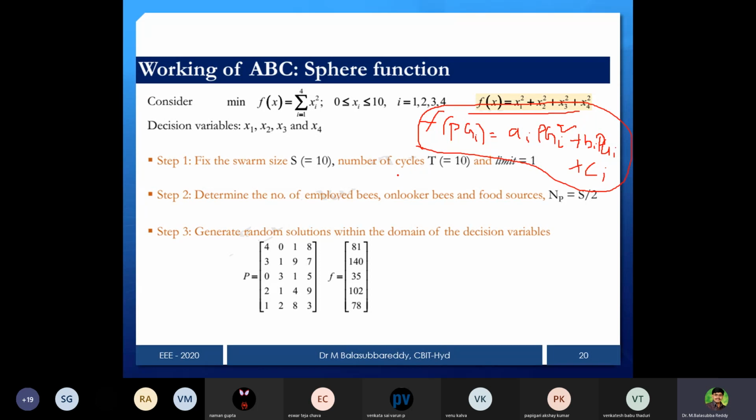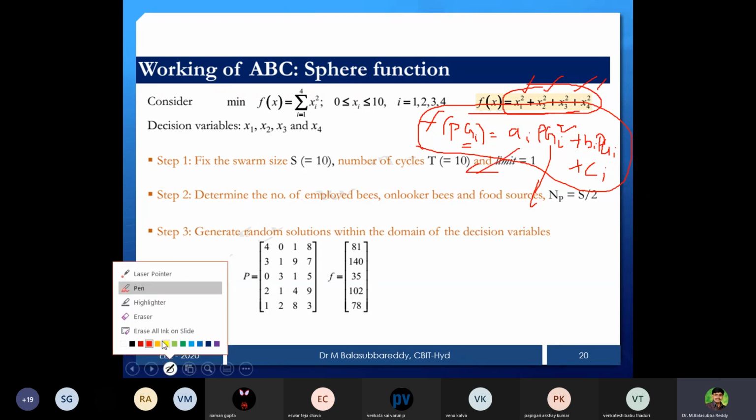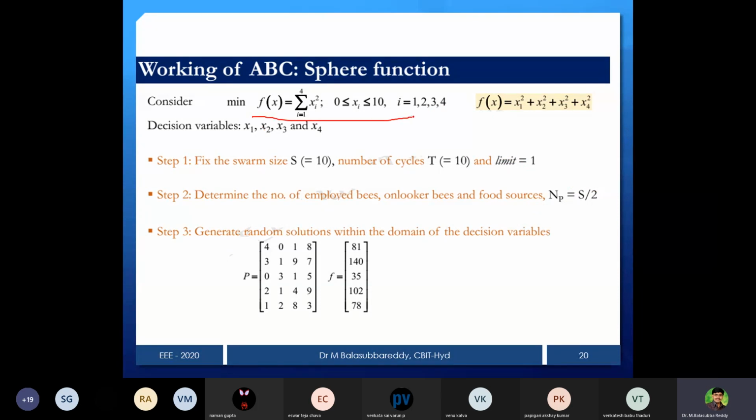We are solving using ABC. Now if we replace this, what we are unknown is x1, x2, x3. In our case, what are the unknowns? Pg1, Pg2, Pg3, Pg4 and so on, because the number of generators is specified based on our problem. In the IEEE 30 bus system, as I showed yesterday, there are 6 generators. You can use those 6 generators, PG1, PG2 up to PG6, like x1, x2, x3. If we expand this up to x6, that problem and this problem are the same. So that is the similarity. That's why it is easy to understand this problem.